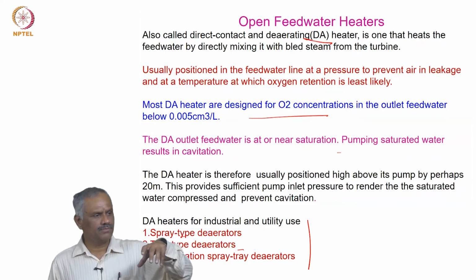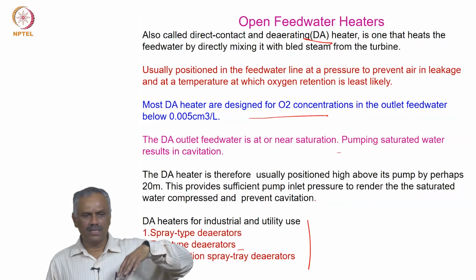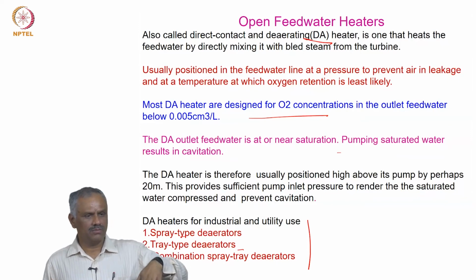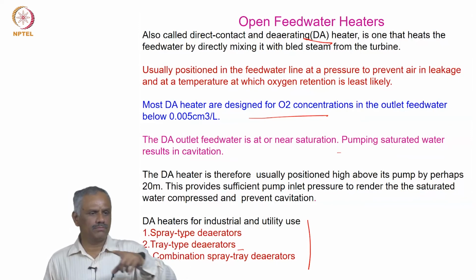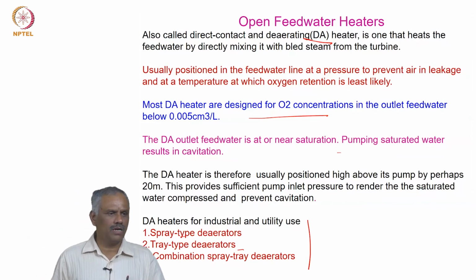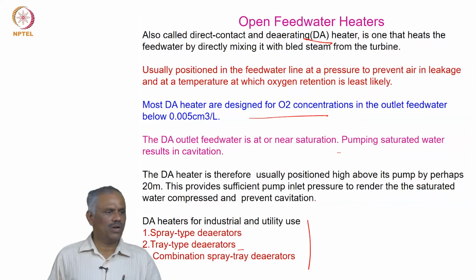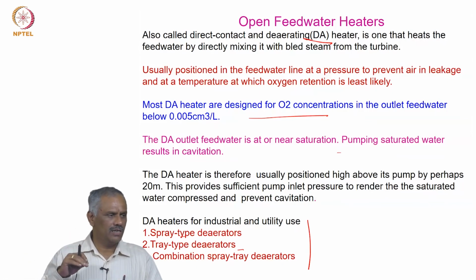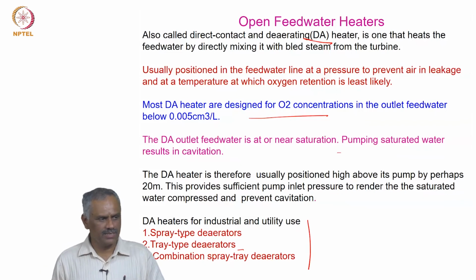Condenser means it condenses the steam which is coming from the turbine. But it is at a low pressure, because the heat rejection should be matched to the atmospheric temperature. So, the saturation temperature of the atmospheric condition, if you match, then the pressure is a suction pressure in the condenser.